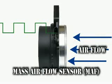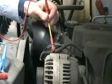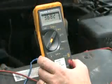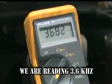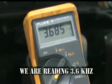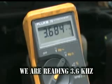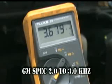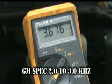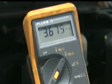This digital MAF sensor produces a frequency that changes with the volume of air passing through it. As you can see, the signal it is producing looks to be normal. Through our DVOM, the frequency of the mass airflow at idle is 3.683 kHz. This frequency will vary based on engine size and speed. The GM spec is 2 to 3 kHz depending upon engine size. The 3.6 kHz reading is a little high and has raised some suspicion.